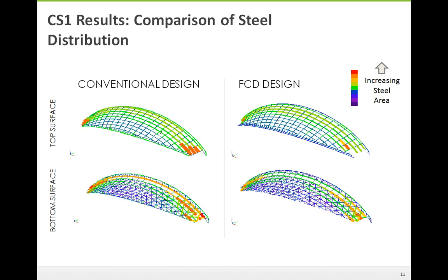It was creating a bit of a hinge in which there was a lot of bending that needed to be resisted. So there's a lot of steel to resist the bending, whereas if the arches were stiffer on top, it doesn't deflect as much, and therefore you don't have local bending at the supports. This analysis was done retrospectively after the optimization was completed to try to understand why the structure was more efficient.